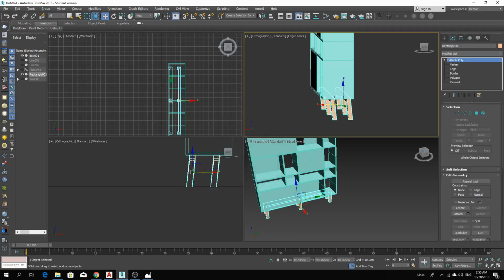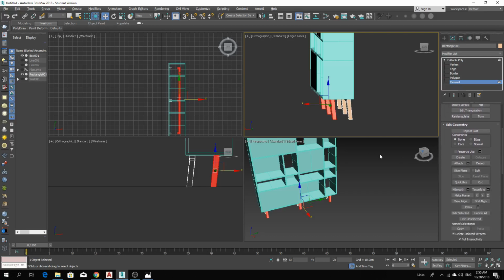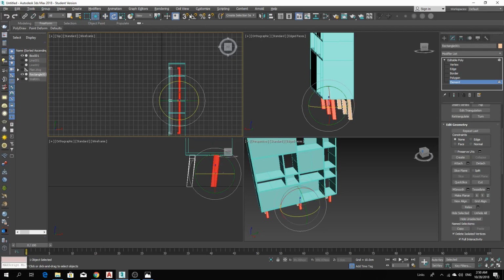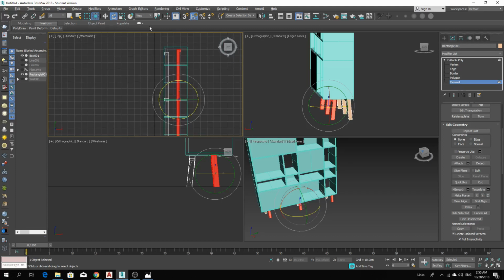So another way to do it, you can either not copy it to an element, you can copy it as a separate geometry, or I would actually just rotate it using the snap toggle to rotate, and make sure that you have rotated 180 degrees.